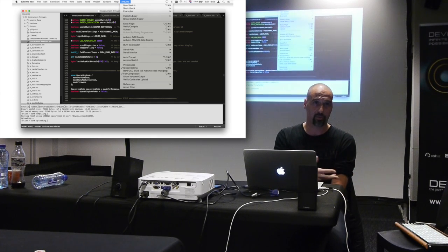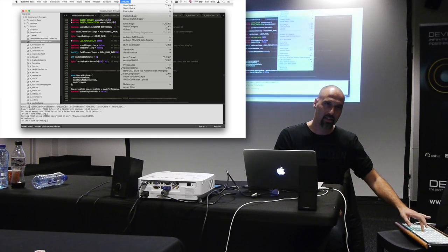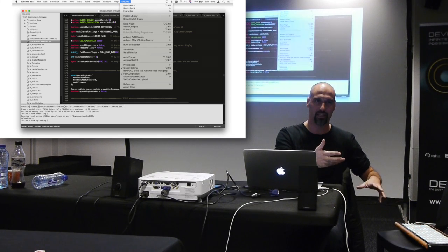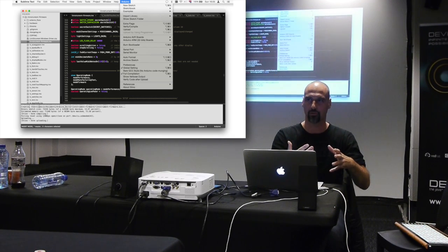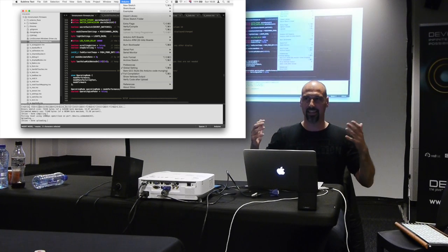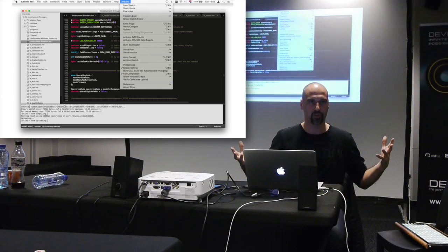because you're working with hardware, as soon as you set a breakpoint, everything stops and nothing works anymore. So for example, in this case, if I would set a breakpoint, I would have no sensor information anymore, no sound would be coming out, I would not get any information sent that is turned into sound, so all of a sudden there's nothing to debug anymore. So it's like the ultimate Heisenberg effect, right? As soon as you start observing or slowing down one part, nothing about your embedded device works anymore.